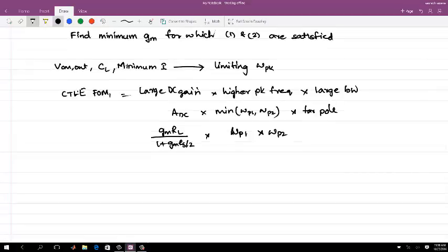Do you see any parameter missing that we want from the CTLE? Anything missing here which you want for ideal CTLE channel loss compensation? So I have only got the DC gain, the peaking frequency, and the far off pole. What is missing in this?